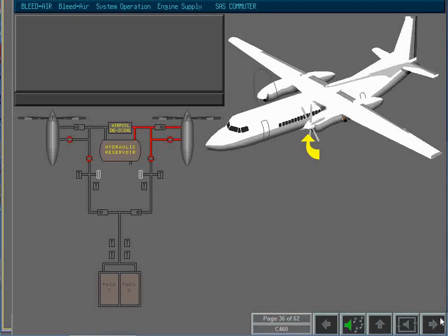Manual engine shutdown stops the supply of air from both bleed systems if the aircraft is below 10,000 feet when the power lever of the operative engine is at takeoff position and takeoff, go-around or flex is selected at the engine rating panel.